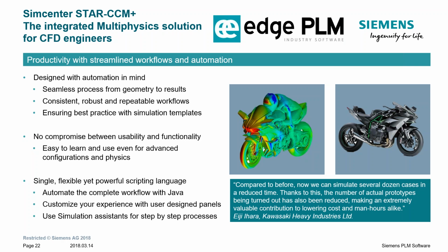You can automatically build a computational mesh on your geometry, no matter how complex, using polyhedral or trimmed hexahedral cells. You can robustly create layers of prismatic cells that allow you to accurately capture boundary layers. You can substitute components of your design as it evolves. You can deploy best practices with tools such as the Simulation Assistant that guarantee consistency between simulations and eliminate analyst-to-analyst variation.